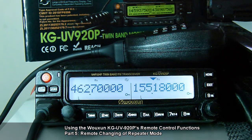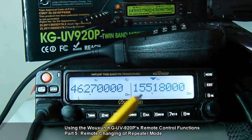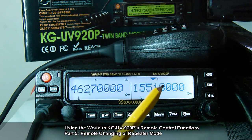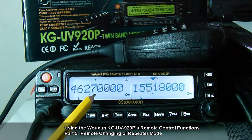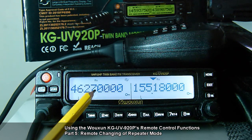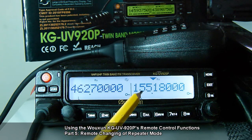Alright, now in directional crossband repeater mode, the flow of traffic would be from our master frequency to the secondary VFO. So since our master frequency is 155.180, we could only transmit one way. So it's directional from the master frequency to the secondary frequency. So the secondary frequency would only be receiving whatever traffic or transmission coming from the master frequency.